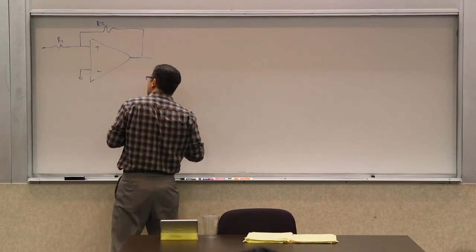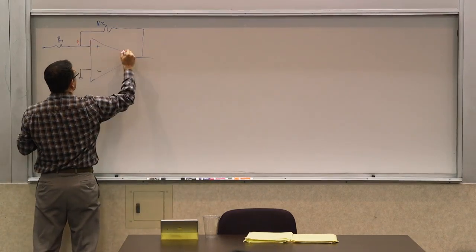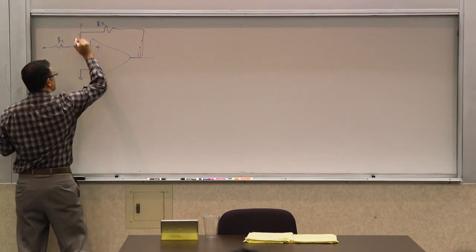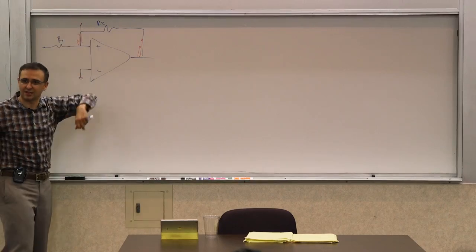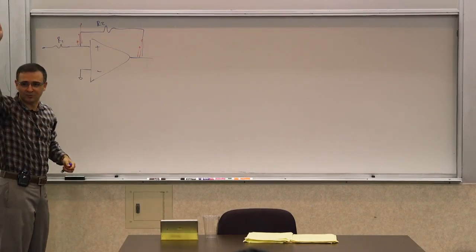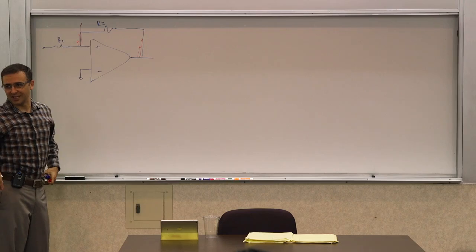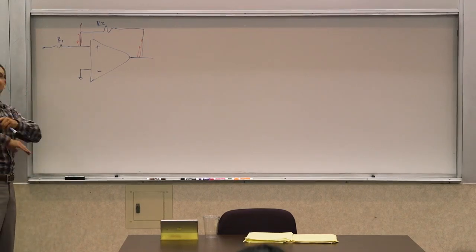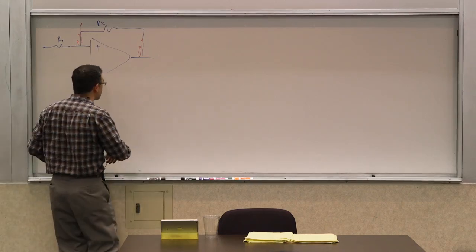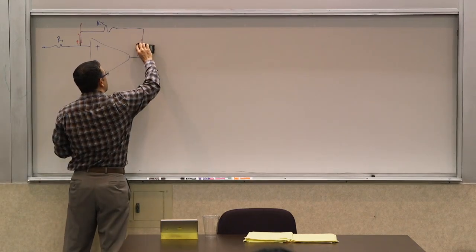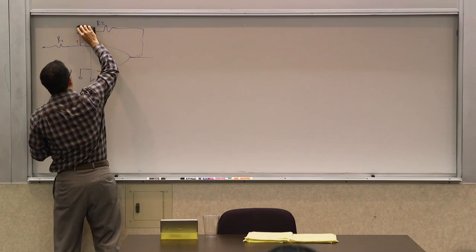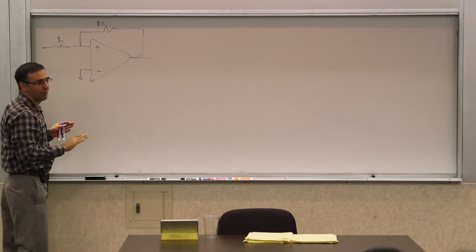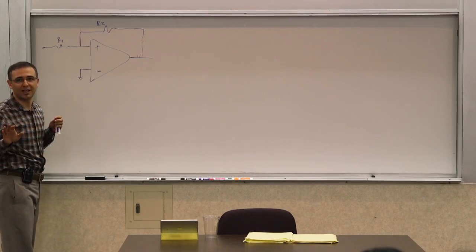She says you have positive feedback. This goes up, this goes up more, this goes up more, till you hit those VCC lines, and then you have something that nicely produces a large positive or negative voltage and doesn't amplify anything. If you go positive feedback, it's a whole different ball game. It's also useful for other things. It was actually used before negative feedback, but that's beside the point in this class right now. But that's not going to amplify. You can do other things, but not amplify.